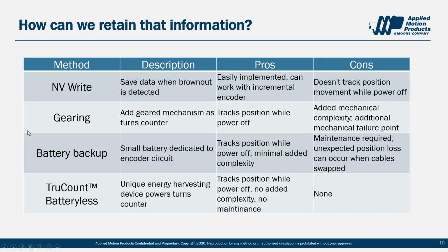So with the battery backup encoder, there's a couple of ways that can be implemented. A rechargeable battery in the cable is a very common one. So the battery will wear down over time. It's usually a long period of time, but it wears down over time. And so if you don't turn the drive back on to recharge that battery, it can wear out. And again, those have a life as well. So there needs to be some maintenance piece where you replace that battery at some interval.